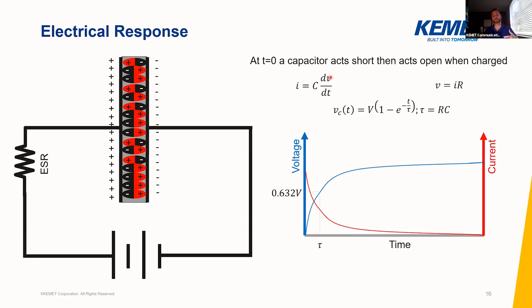Many times you can actually find that out from the operating device, sometimes known as the slew rate. If you can get a sense of that, in many ways that is the inrush current right there, how far up that current will spike. So multiplied by the capacitance. In order to effectively do that, you have to know essentially how quickly you're turning that voltage on.